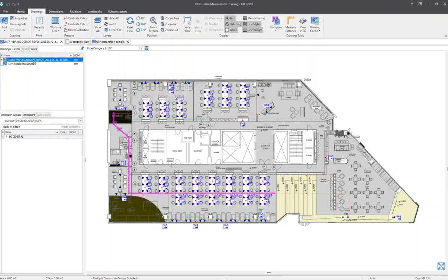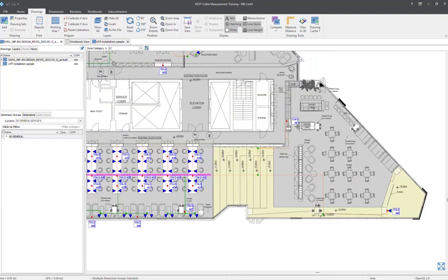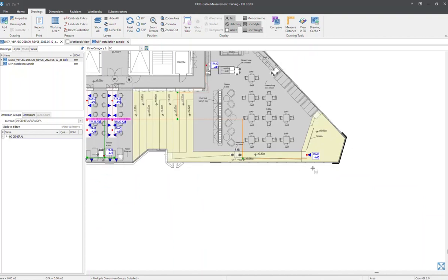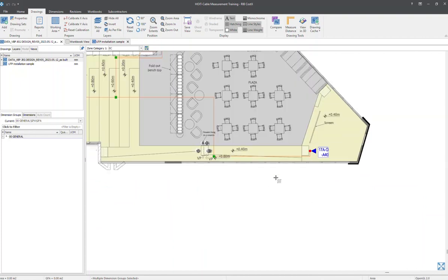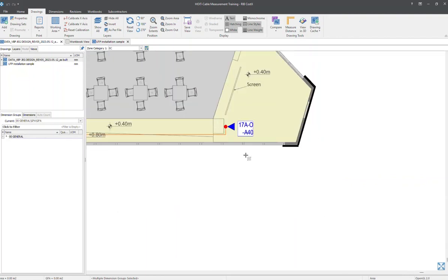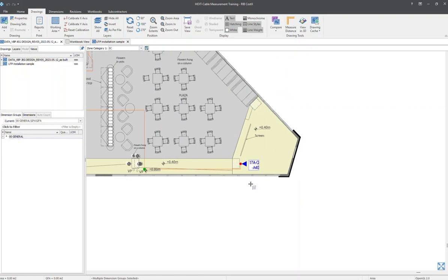The first type of drawing is in the CAD drawing format. Normally, if we are using CAD drawings, we can have what we call the ratio information. Normally the CAD drawing will indicate the ratio, like what scale we are using. So basically, the first thing that we need to check after we import the drawing is the scale, whether we are using the right scale or not. In this case, we don't have any information related to the scale.